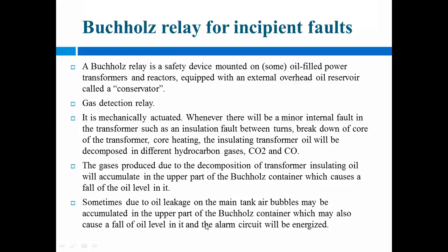There is an alarm circuit. If any fault occurs in the transformer, this relay senses it and gives an alarm, so that we can manually turn off the supply to the transformer. That's why it is called a manually actuated relay. This Buchholz relay is a manually actuated relay.